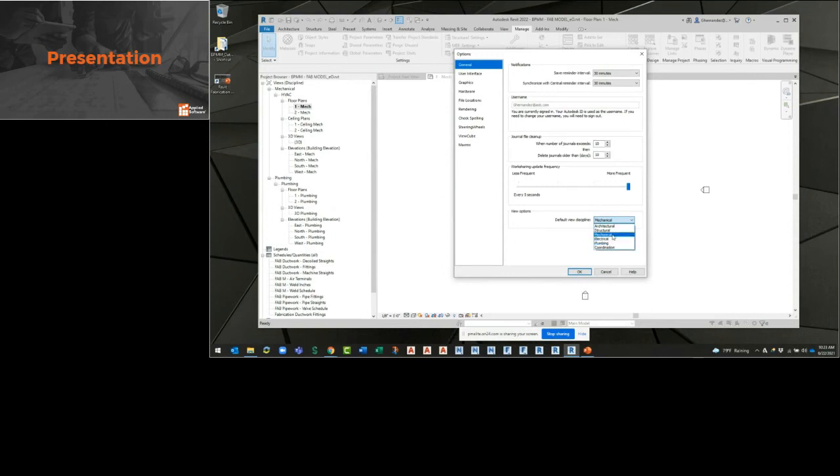It'll force the views that you create, like the selection box and the custom 3D views that you make on the fly, to default to mechanical, and they're not architectural or coordination where you're not actually seeing the content. You're seeing the walls and structure, which is not what you want for fabrication.